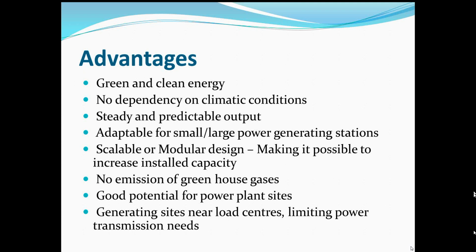Moreover, it is scalable and modular in design. Now, why do we say it is scalable or modular? The efficiency of the power plant can go up or down by altering the number of membrane modules. So, suppose there is a need for high power to be generated from the same osmotic power plant, then the number of membrane modules can be increased in order to have a greater head. In a similar fashion, if we need a lesser capacity, then the number of membrane modules can be reduced.